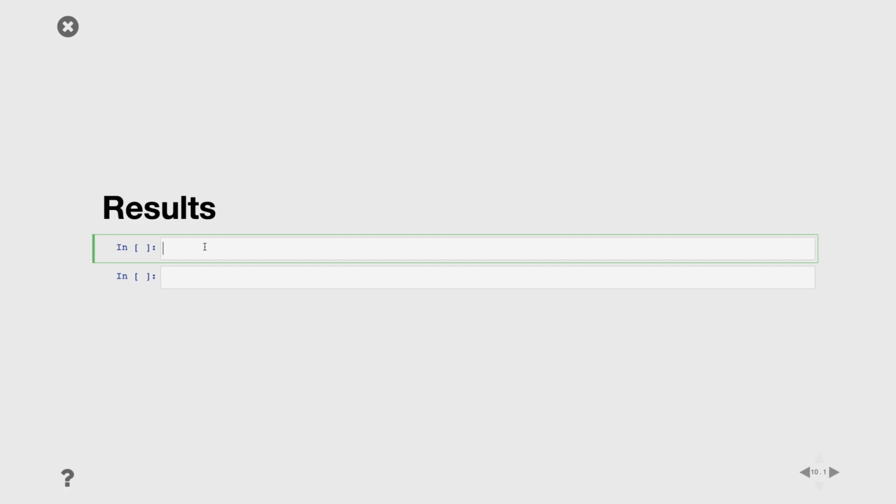So when you're getting the solution out of Polyfem, what you're getting is a solution sampled on mesh dots. So what we will be getting is some solution points, solution triangles, and the solution itself, which in this case will be a displacement. And to get it out, it's just solver dot get sample solution. So we can get the sample solution out of it.